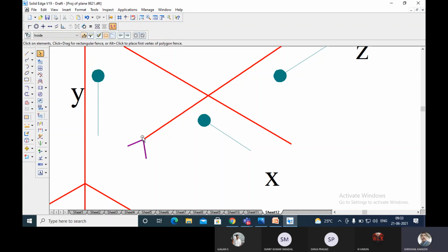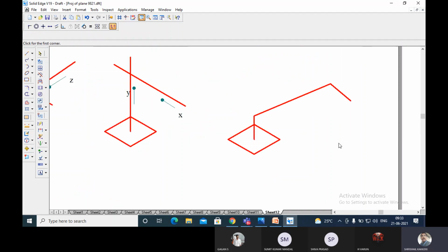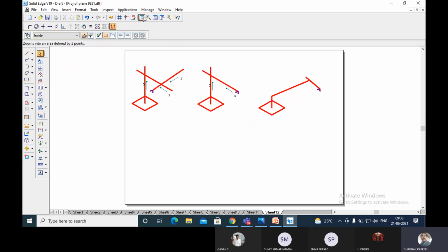This is called the end effector of the robot, and I'll write this for all of these. It will have a rotating joint here, and rotation here also, and the arm can be moved front and back. You can see here, the arm can be moved front and back. It will be linear and rotational, and this will be rotational. This is called a spherical coordinate system.